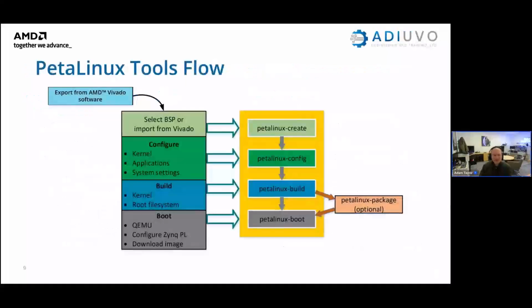So I'm going to skip over to this, and I'm going to show the build flow now. The build flow that we're going to go through is very simple, and this is going to be nice and straightforward for us. We're going to design our hardware in Vivado and export it just like we would normally do. Thank you very much to the person that just put the user guide in the chat. We're going to capture the design, then generate the bitstream and export it from Vivado into that XSA.